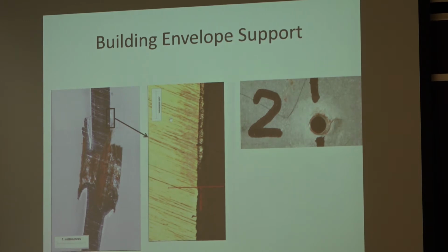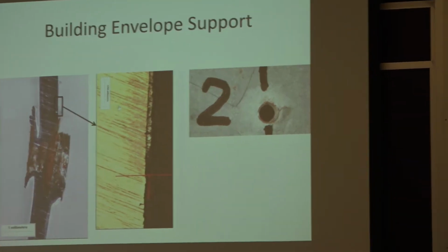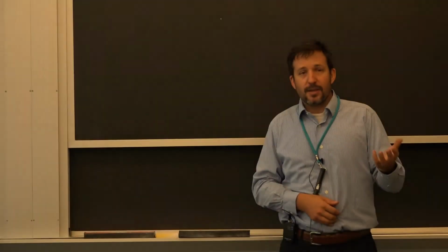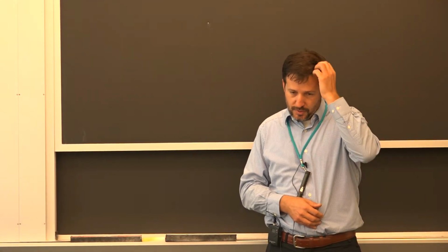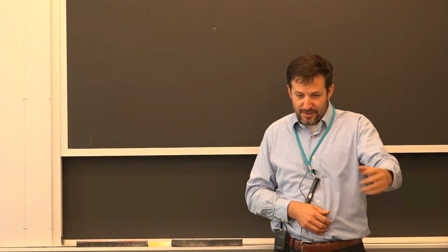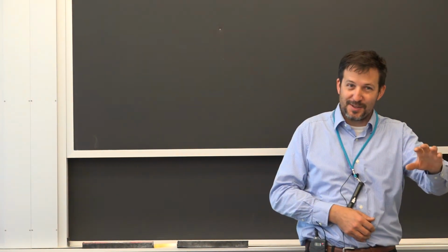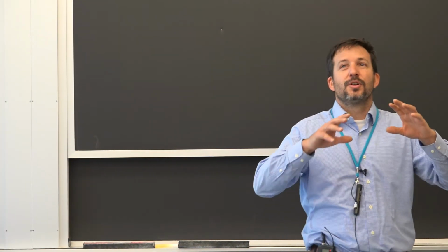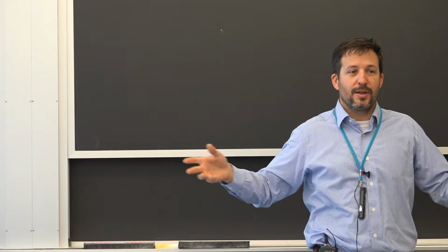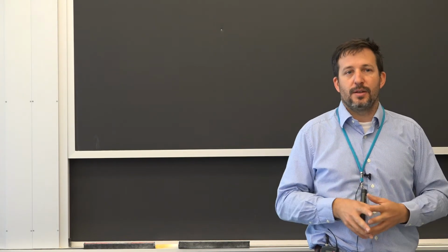Yes? Would it almost be better to be immersed in water so that it's all in a single electrolyte? Yes. The question was, as far as the benefit of the galvanizing, would it be better for the building to be submerged? So yes, if the building is submerged, it's going to be able to consume all that zinc because it's really shared in the electrolyte.